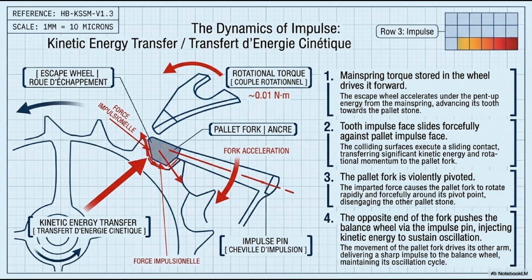Notice the Swiss lever's contribution here. Both the tooth impulse face and the pallet stone impulse face contribute to the energy transfer. This is shared impulsion, partagée, distributing wear and friction between two highly polished surfaces.